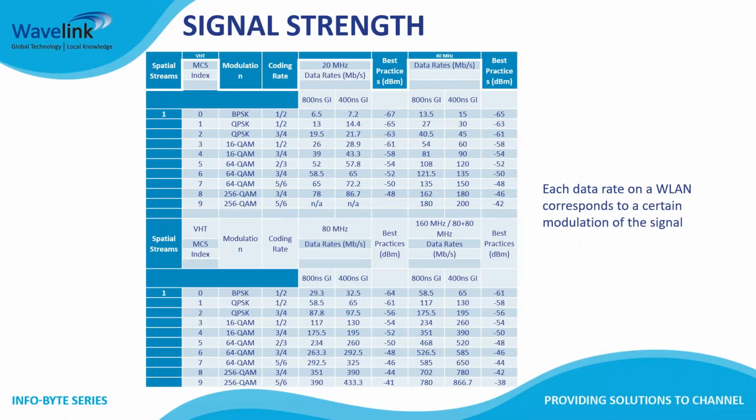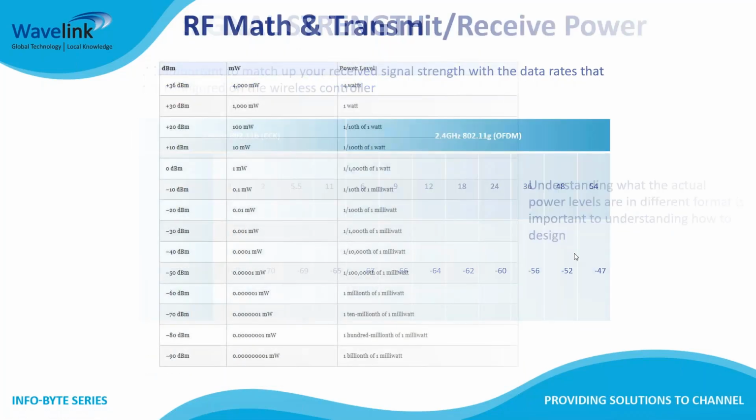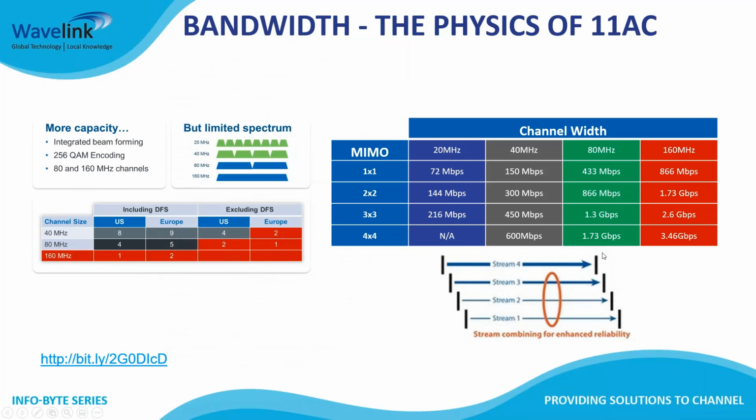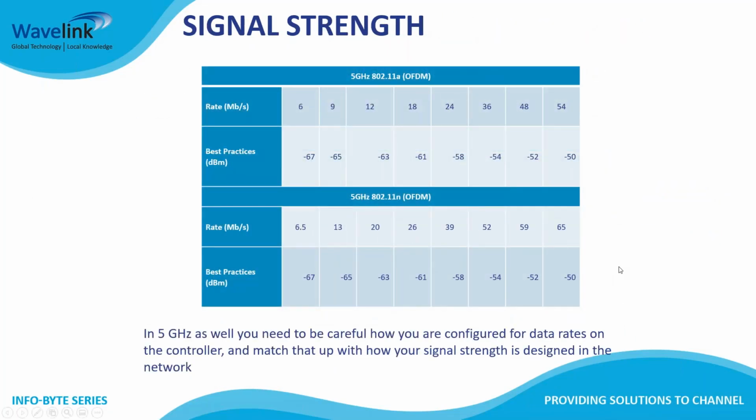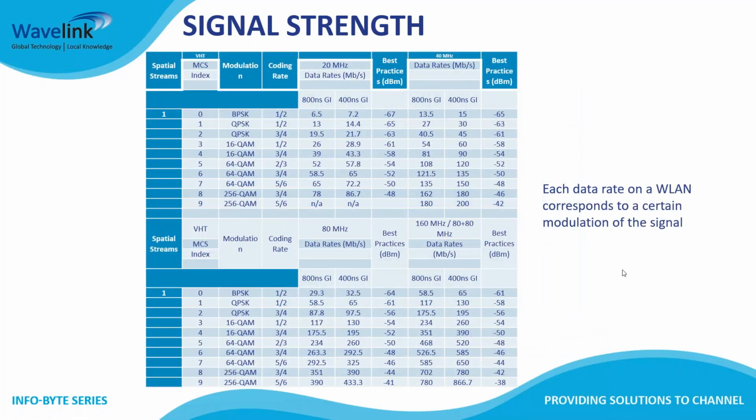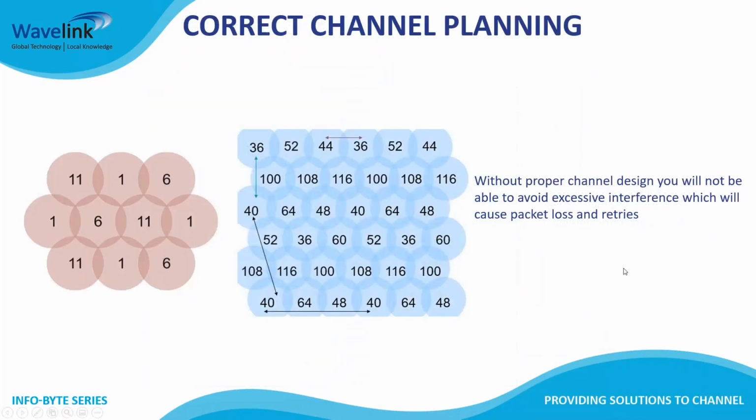And then we just get a little bit crazier. Again, this is looking at different types of modulation for 802.11ac. This is where we start to get into 64 QAM, so quadrature amplitude modulation, how many spatial streams we're using, etc. So this is when you can start to actually see your higher data rates. So again, what starts as a nice simple slide to explain things in simple terms starts to get a little bit crazier when you start digging into the proper values themselves.